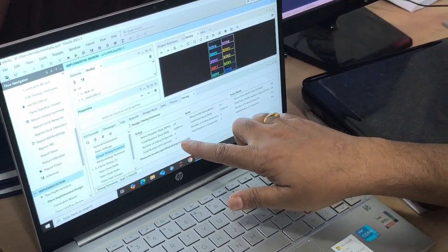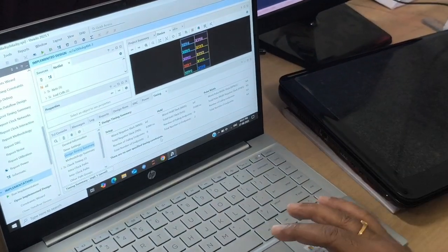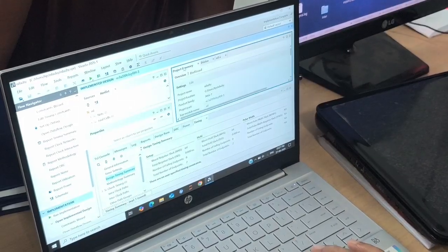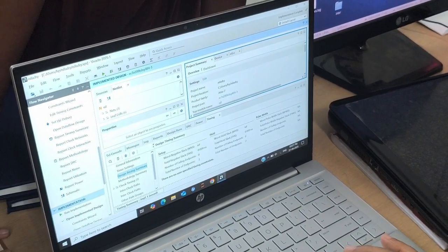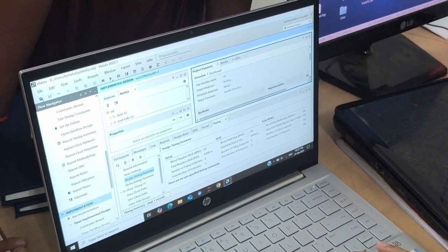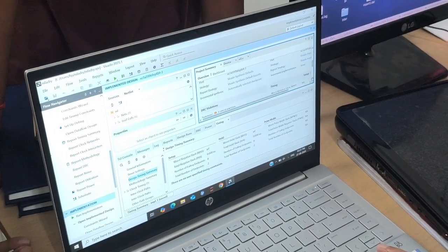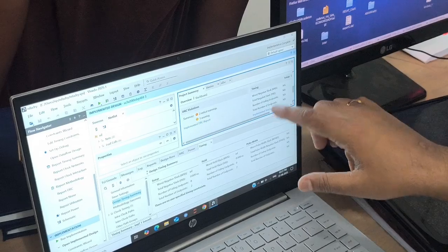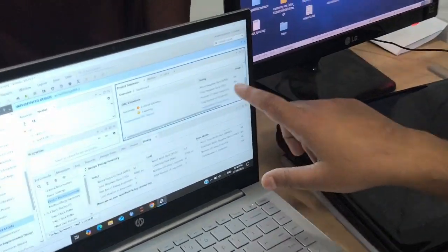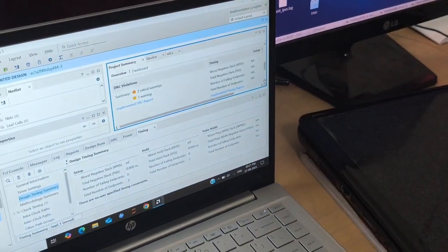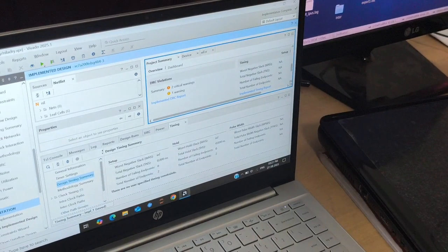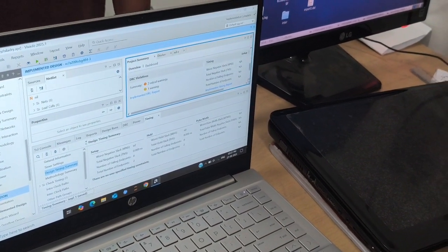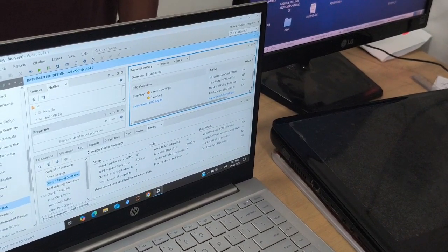The total number of endpoints is 2. So this is the timing report they are showing, and here the project summary. Now you can see some timing. Previously nothing was there, before run implementation. So now some worst negative slack. Always remember that the slack should be positive. If the slack is negative, then the constraints are not met.